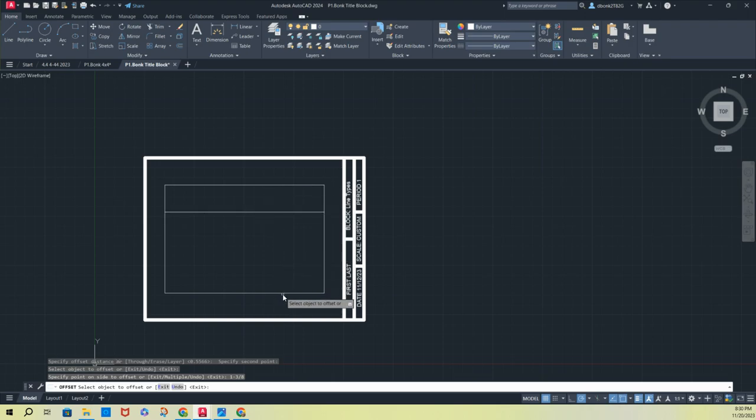I'm going to click the bottom one, go upward, same thing, 1-3/8. So those are 2 1 3/8 offsets. These on the sides, the offset is 2 5/8. So it's 2-5/8 inward, opposite side inward, same thing, 2-5/8. And then you're trimming away what you don't need, which is you just drag through with this trim tool.